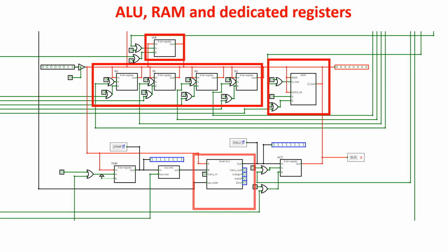Here you see the ALU with 2 inputs connected to the bus. Input A is directly connected to the bus and input B is connected to an element called bus 1, which puts the number 1 on the bus when we want to increment by 1 the instruction address register, an operation we do every stepper cycle.